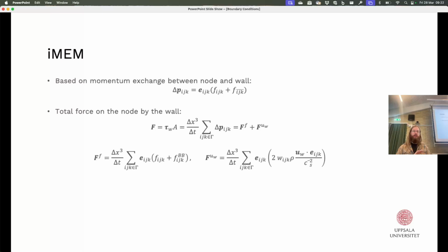We never touched viscosity in this entire model. We don't need it. Actually, we are using some of the most advantageous features of lattice Boltzmann, namely that it always deals with the flux density tensor. So this question, how do I actually compute friction in the Navier-Stokes equation, where I have to integrate the pressure and the stress together, is not necessary here. So you avoid a lot of the nastinesses of other approaches.